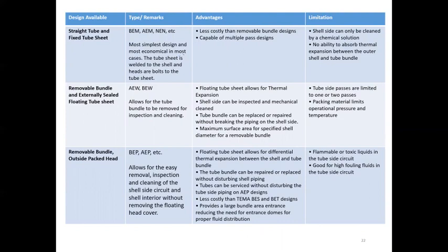Okay, this is the simplest design and most economical in most cases. Okay, the tube sheet is welded to the shell and head bolts to the tube sheet. The advantages are first, it is less costly than removable bundle design, and it's capable of multiple pass designs.